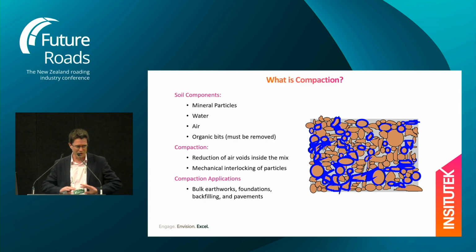Hopefully we've got no organic matter. The objective of the compaction process is to reduce the air voids and also to create better interlocking between the particles. And it doesn't matter whether it's bulk earthworks, foundations, backfills, which we've just been talking about, or pavements, it's the same.